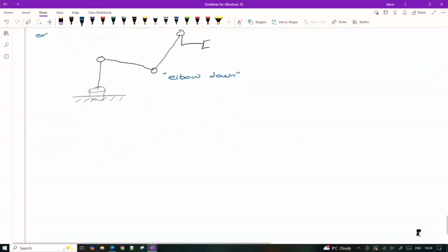So if we think about the robot, what we're looking at, and I'm not going to do the full solution here for obvious reasons, we have the base revolute joint. We'll have a cylindrical joint that sits on top of that, that's connected to another revolute joint, a revolute joint on the base, a revolute joint that sits on top of that, and then another revolute joint, and then that out to our end effector mount point.